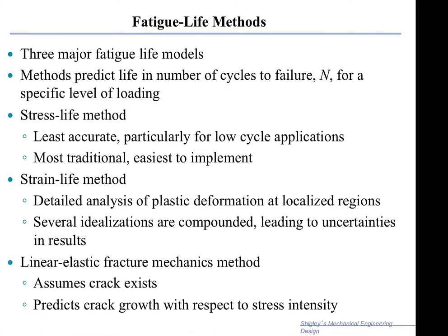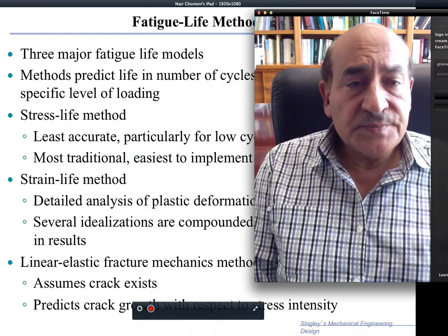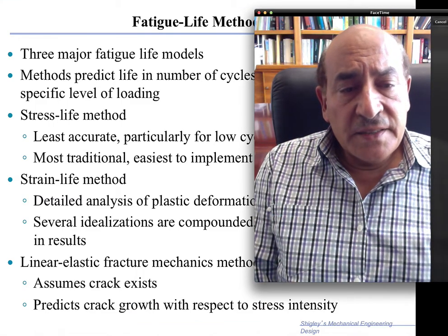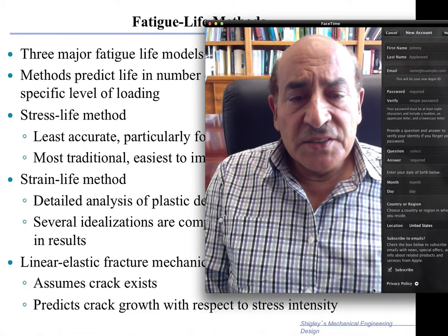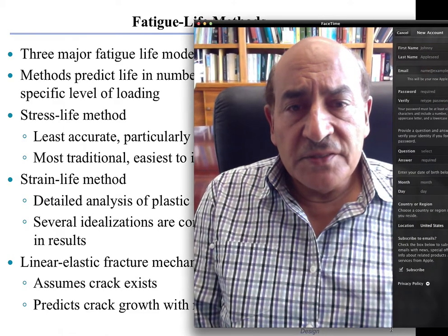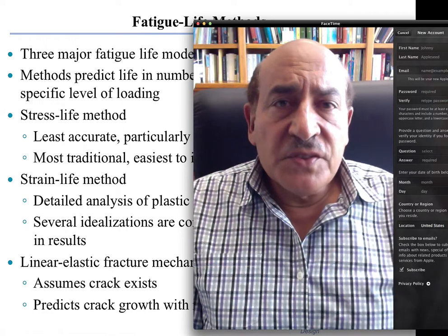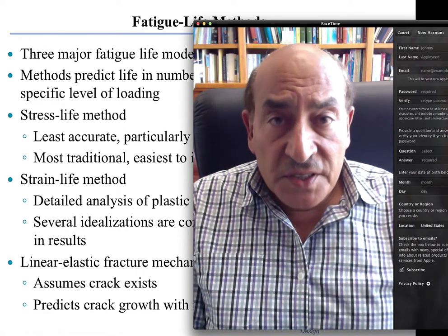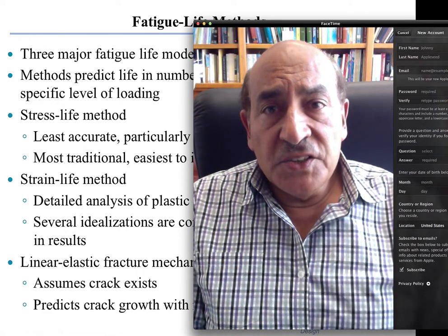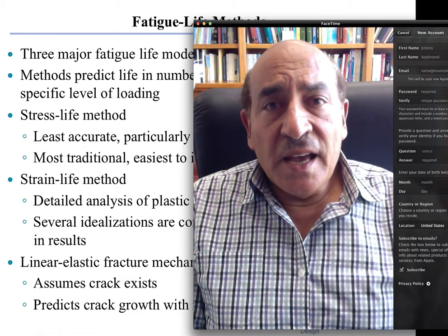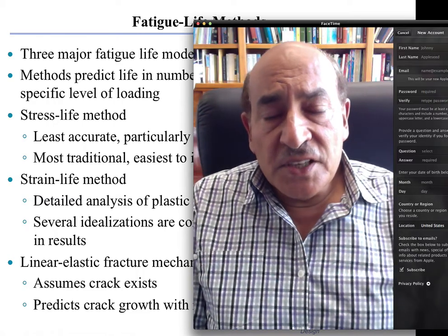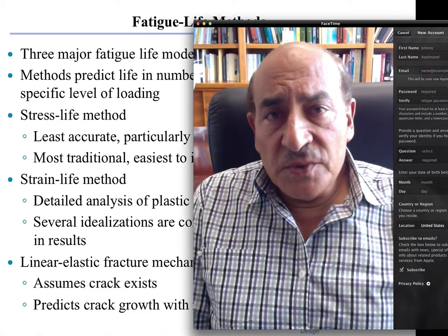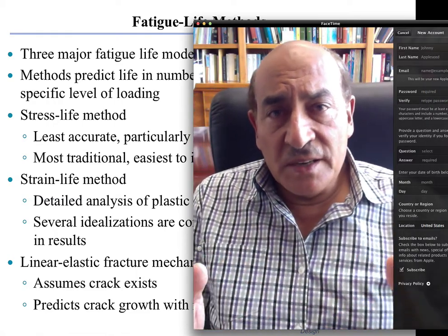So from these examples that we've seen here, it appears that we really have to understand fatigue in a qualitative fashion. We have to think about the origin of the initiation of the cracks, where they initiate and how they propagate. And generally speaking, we are dealing with either ductile materials or brittle materials.